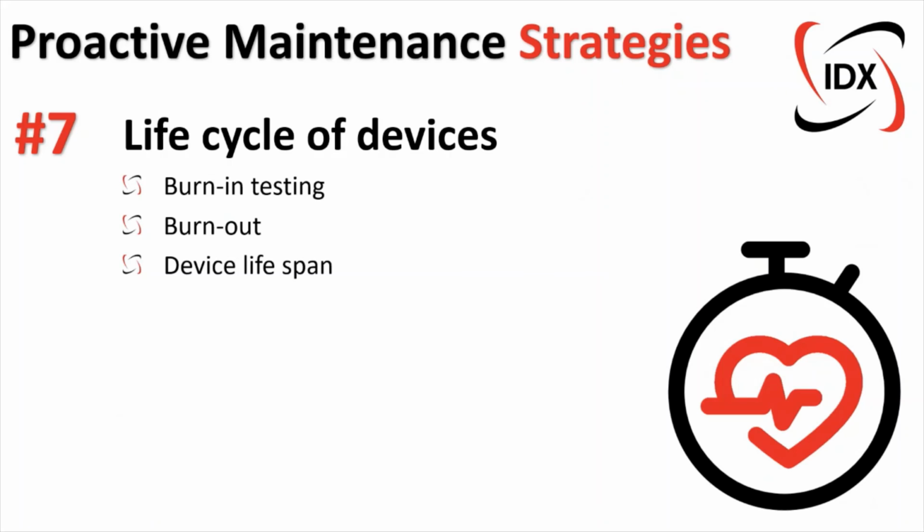Device lifespan. If you look at the mean time before failure of various different components installed in a network, it might range from 15 years to, I've seen components that have a mean time before failure of 146 years. And I find that very unlikely, but that's probably what all the electronic components in the device are rated to. So device lifespan, from our experience or from what I've seen, is typically about 15 years on a PROFIBUS network.